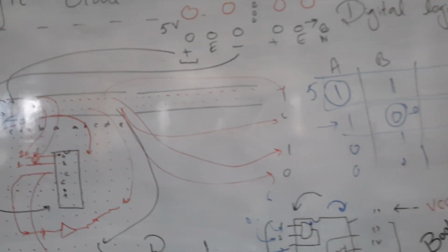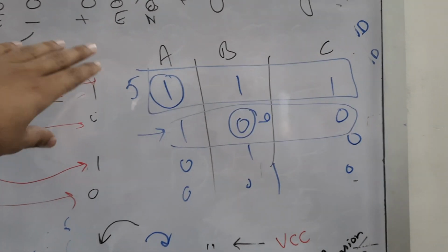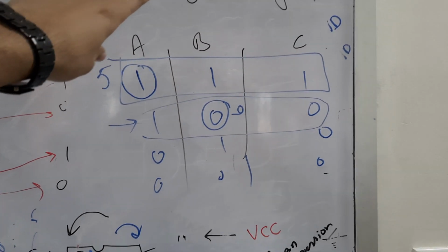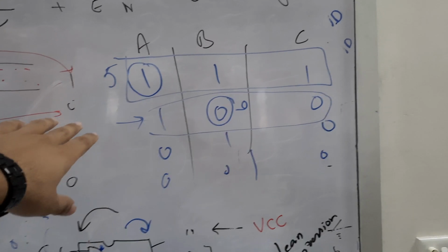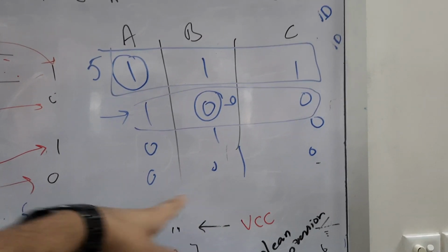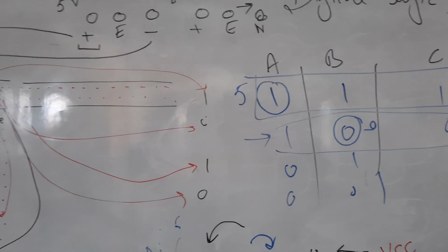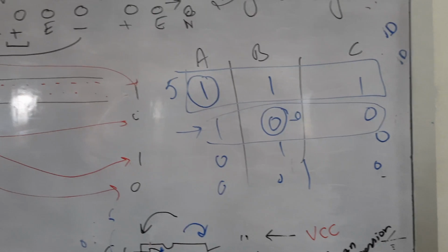Then let's move on. There are different types of gates. For example, there is an AND gate. The truth table of the AND gate is drawn here. If both the inputs are 1, it gives 1. If any of the inputs is 0, it will give 0, and obviously on both 0 it will give 0 as well. So you will be given multiple ICs, you will see their behavior, you will give them inputs and see the outputs.